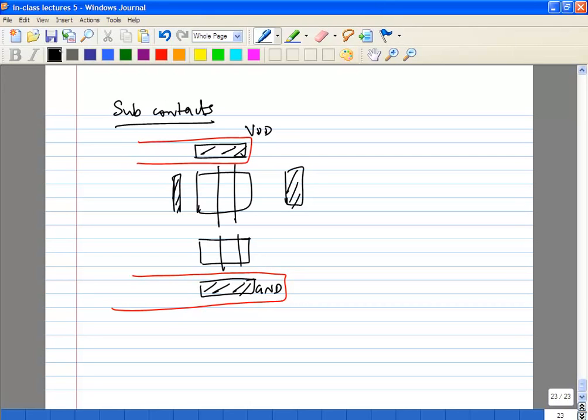So you want to give a very good substrate contact. Typically, there will be specialized RF transistors which are very well modeled. If you look at the basic transistor model, they basically just model all the way up to M1, probably just enough to give contacts and connect it out. Any metal lines added on top are not modeled. If you add substrate contacts, they are not modeled.